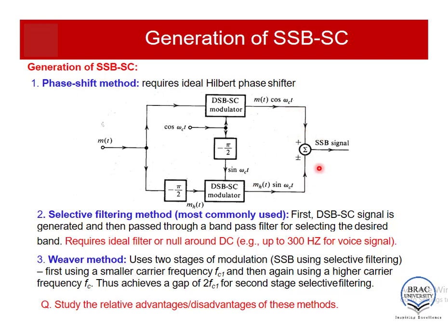summer. Then we have two options. This is always plus, but we have an option in this case. If we want the USB signal, we will choose the minus sign. If we want the LSB signal, we will choose the plus sign. And finally, we have got the SSB signal as the output of this summer.